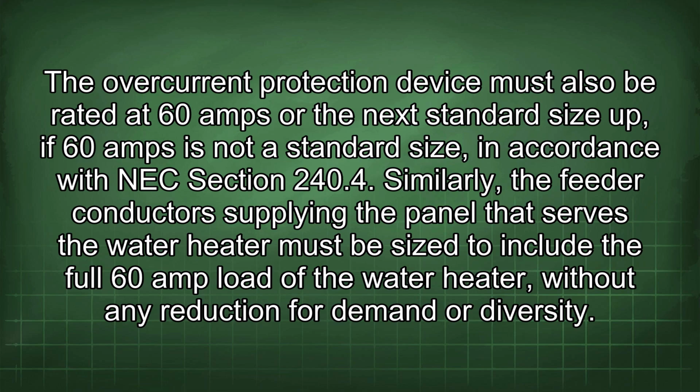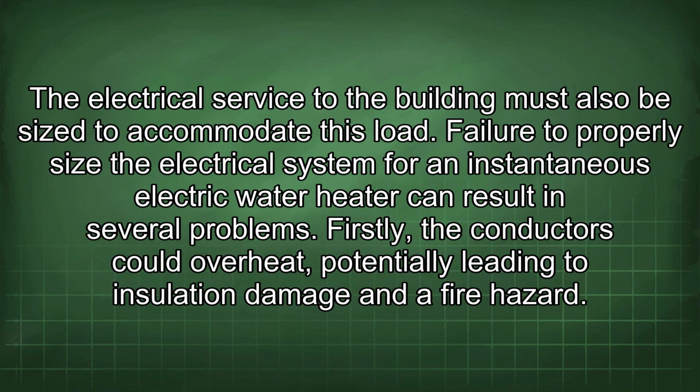Similarly, the feeder conductors supplying the panel that serves the water heater must be sized to include the full 60 amp load of the water heater without any reduction for demand or diversity. The electrical service to the building must also be sized to accommodate this load.